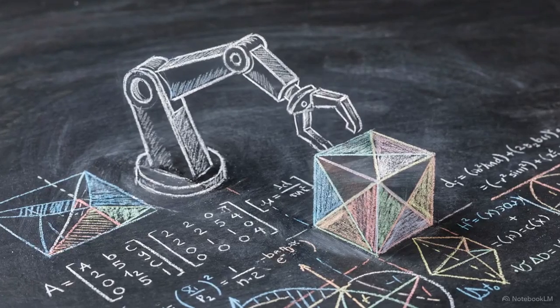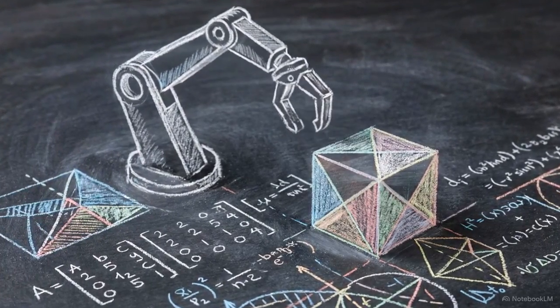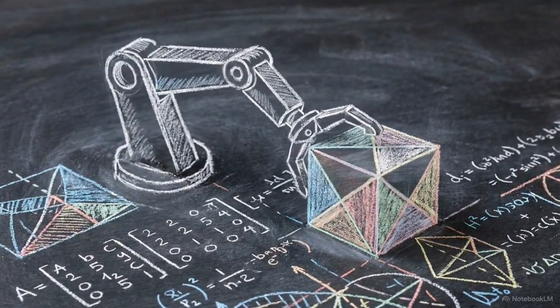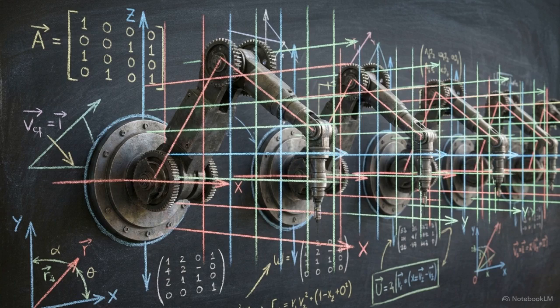To pick up a virtual object with a physical machine, the software maps the headset's local movements to the global world space, and then translates those coordinates into the robot's local base frame. Without continuous matrix synchronization, sub-millimeter interaction is impossible.